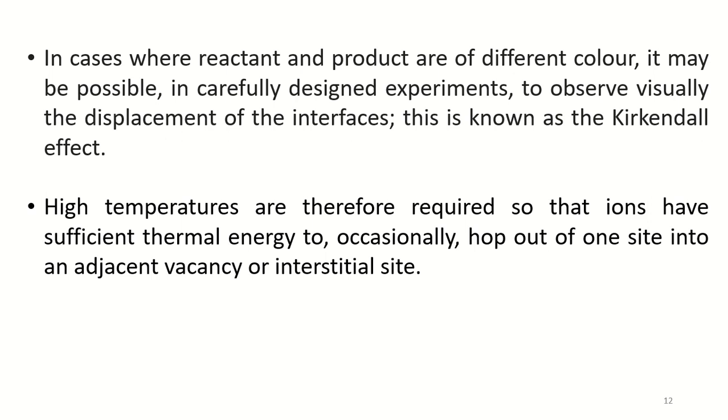Defects in both reactants and products are required, particularly vacant sites for adjacent ions to hop into. High temperatures are therefore required so that ions have sufficient thermal energy to occasionally hop out of one site into an adjacent vacancy or interstitial site.